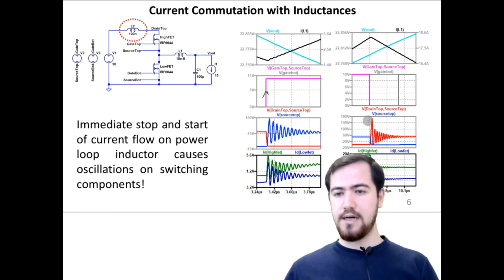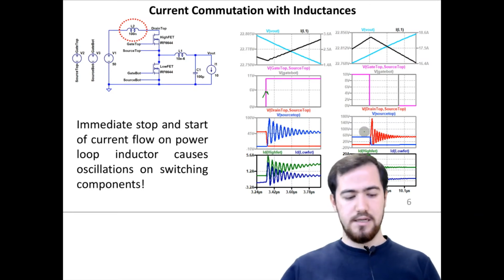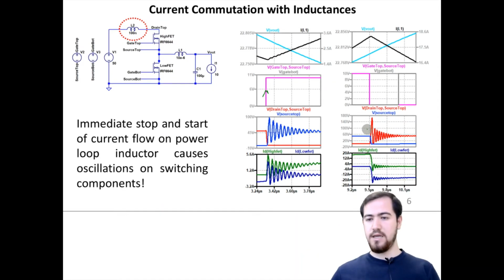When we check the other transition period, let me show it in a better way. The oscillation voltage, the overshoot voltage, actually exceeds 140 volts. However, the transistors used here, the EPC2033, are rated at 100 volts. So this means an overvoltage breakdown for our switches. So we need to solve this problem before starting the implementation of this circuit board.